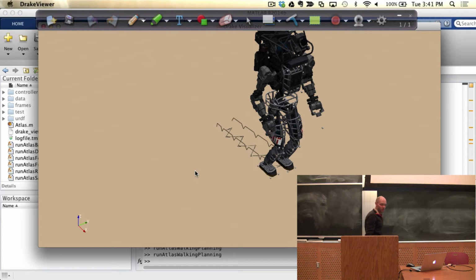Hopefully not a barbell, but when we first started playing with this, before you understand the parameters of your robot, we asked for the center of mass to be kind of high, and we had walking that went like this. We called it happy walking, but the arms always went up in order to keep the center of mass. They're heavy arms, so you can get a lot out of that. But then you find the nice sweet spot, and those go away.